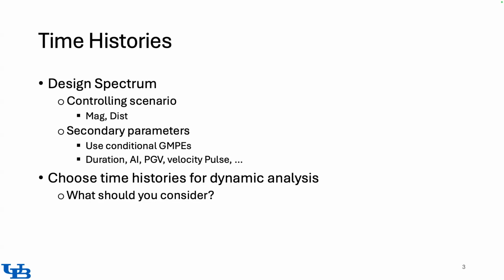But if you have a more sophisticated model that requires a time domain numerical solver, then you need to have a time history as input. So now that we have characterized the ground shaking, we need to find time histories that are consistent with the scenario that we have identified contributes to our hazard and use it in our analysis. So that's the goal.